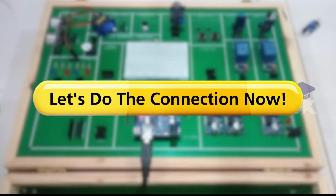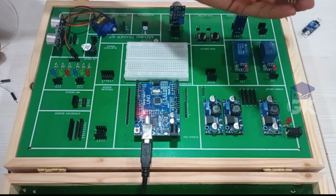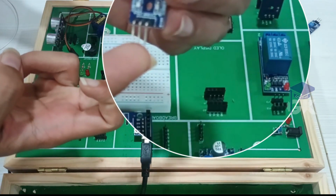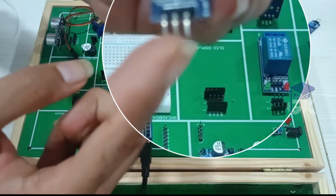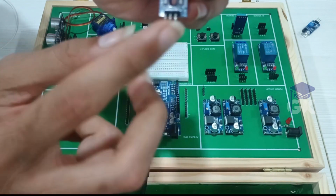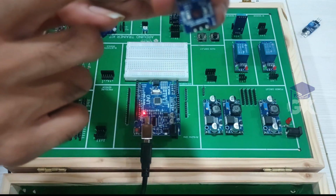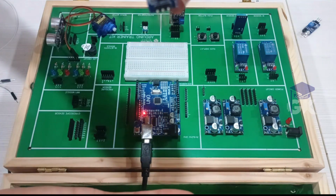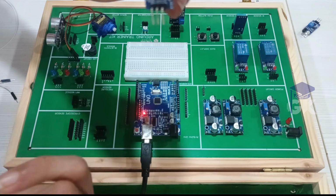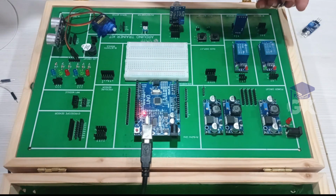IR sensor module. So let's start the connection. As you can see, this is the IR sensor, in which you can see 3 pins: output, ground, VCC. This works on 3.3 volts, and you can see a potentiometer to change the sensitivity, and we can see an IR transmitter and an IR receiver. It sends the data in infrared light and takes the output by using the receiver. So let's start the connection.